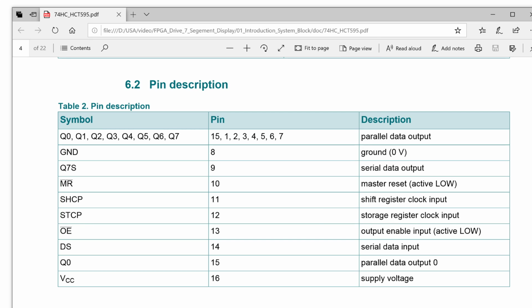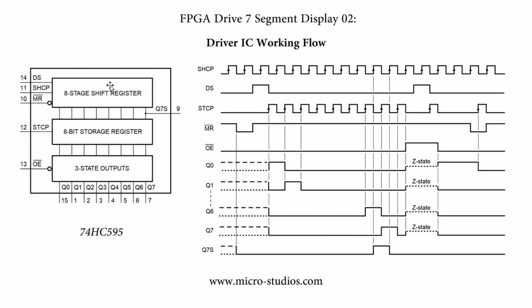The most important thing we must remember is that the shift clock controls this register, and the storage clock only controls this storage register, whether it outputs or not.